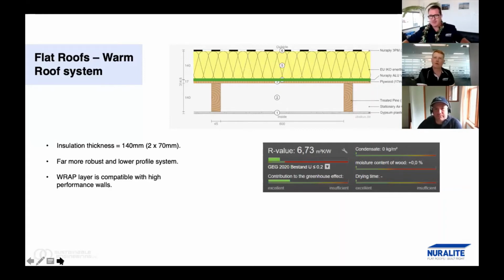As Jason's previous slide showed us, the building science slide there, we're talking about stopping that warm, moist air rising up into the structure, into that cavity, and that's what that green line does. So, in our case, it's actually a full aluminium foil vapor blocker. So it's not smart. It doesn't breathe one way and go the other way. It does absolutely nothing and just stops everything, which is appropriate below a PIR layer. Yes. So it's the right thing to use. Yeah. So that's fine.